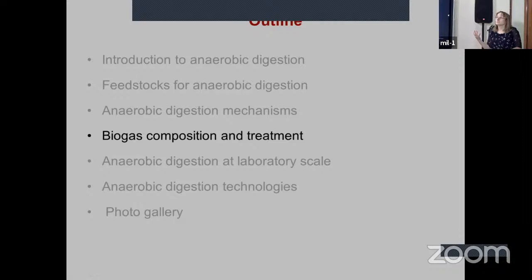If you want to control these bacteria, you go more to classical fermentation for food processes. Then you will need some sterilization of the waste, according to the amount introduced into the digester, and also the high price of sterilization towards the quite low price of methane, I think it's not very worth trying to do it.